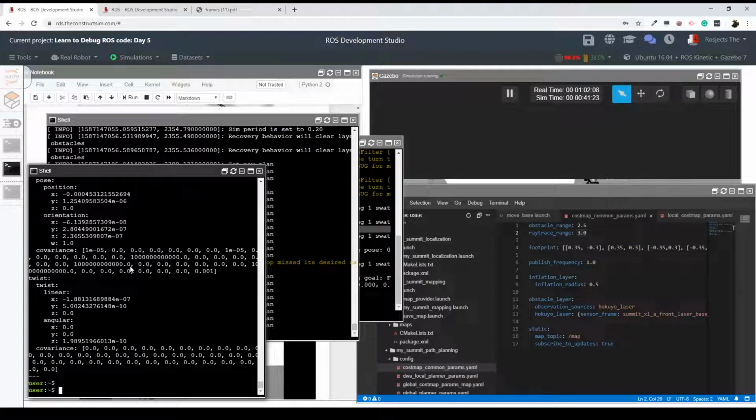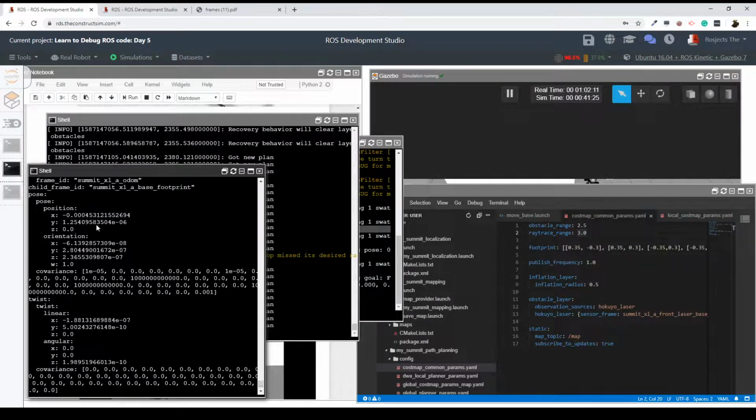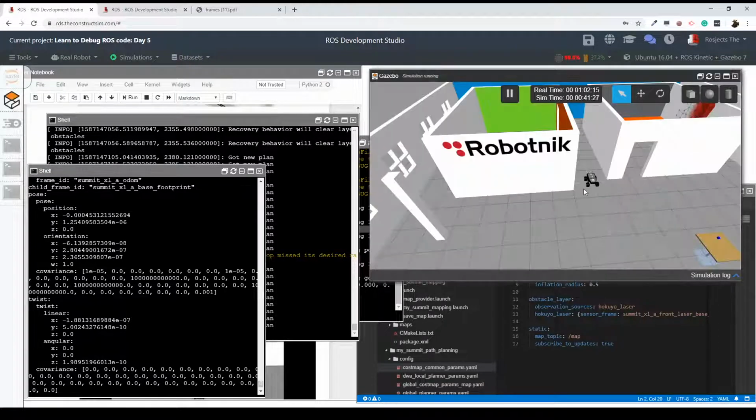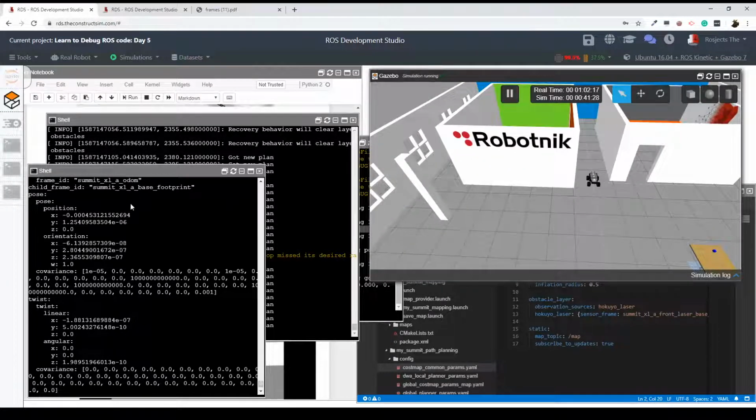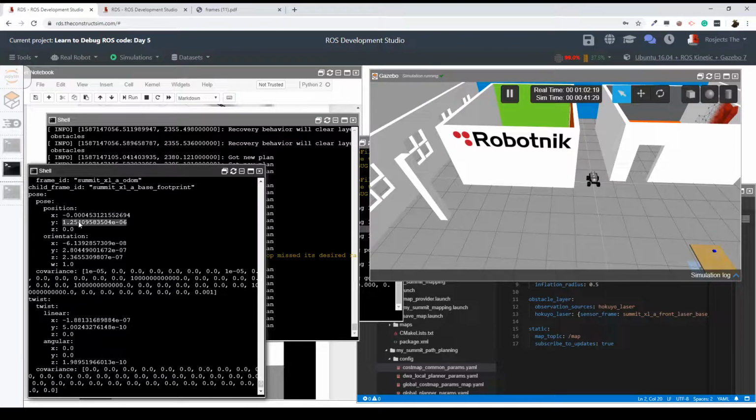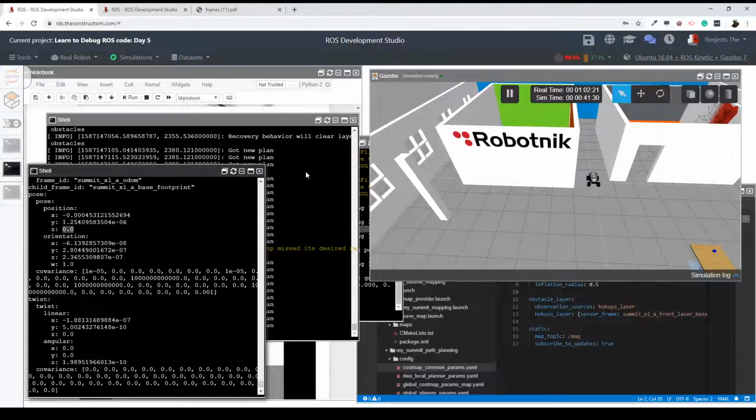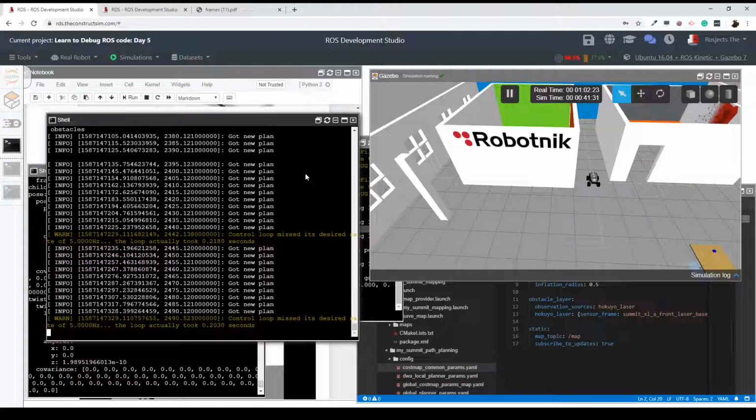always, you're going to see here, the same. So it's 0, 0, 0. Why? Because the robot is not moving. The robot is at the 0, 0 position of the simulation. Yeah? You can see here 0, this is a 0, and this is a 0. So, in this case, the odometry topic doesn't help me. Some problem with move base.